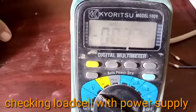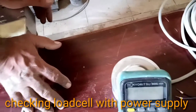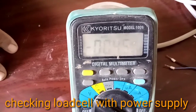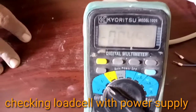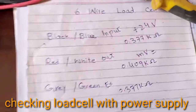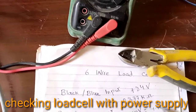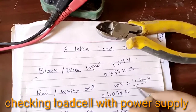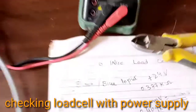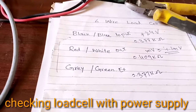The millivolts vary. So this shows our load cell is in 100% working condition. You can see more, 4 point something, 4.6, 4.7. So I can write here millivolt 4.1. This shows our load cell is 100% okay, and you can check by adopting this procedure for load cells on your table.